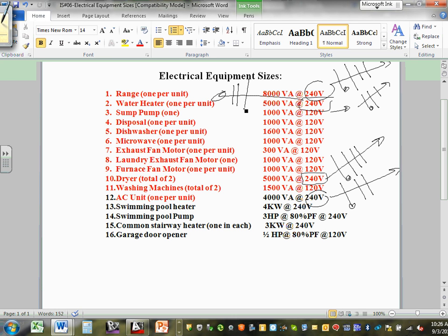Do you see them? Are they here? Bottom stairway heater, second from the bottom, 15. Okay, 15. Yes, thank you. That's why I did highlight it. These stairway heaters also need a ground and a hot and a hot. These are the only 3 places where you don't need a neutral. How do you know? You basically have to have wired them.